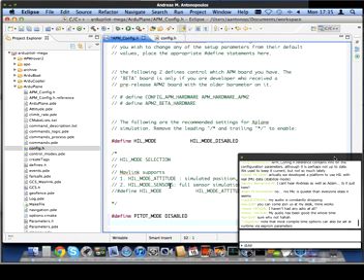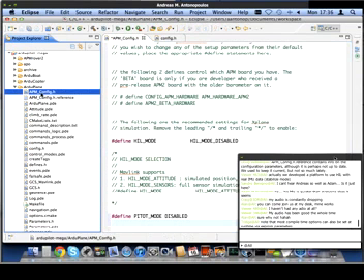Now, a lot of these, as Tridge mentions, are actually reflected as runtime parameters. So when you're looking in your ground control system and you look at the parameters page in configuration, you have this long list of parameters. Many of these can be defined at runtime. But if you want to just hardwire them in the code, APM config.h is the file you would change.